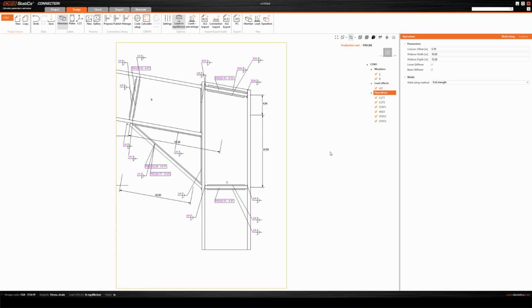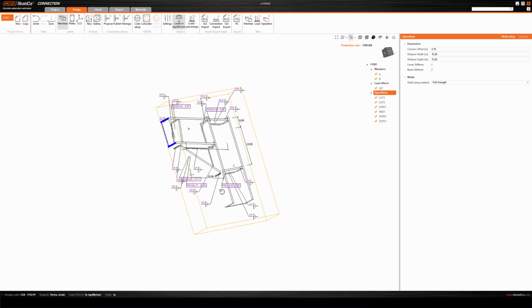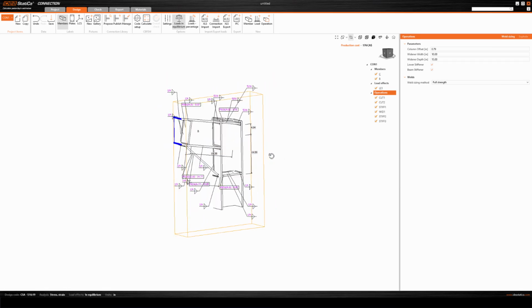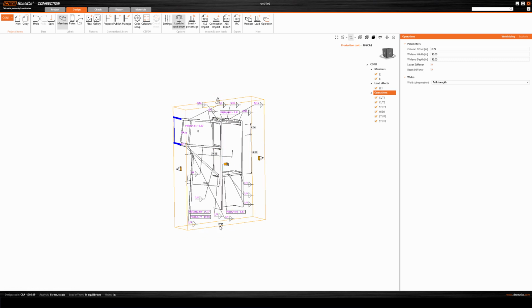There you go. So now I have the section, and as you see, if you compare this drawing with older versions of our IDEA Statica, you will see that this drawing is much cleaner and it has more details. So all of the weld sizing, the dimensions of plates, etc. And as you know, you can also, using this option, modify the drawing as you see here. So I can make it smaller, control the drawing dimensions, drawing sizes, and details that we want to see in this sketch.